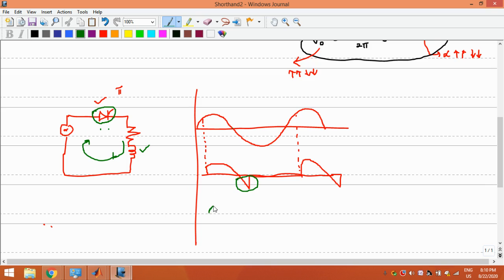So if you draw the current, I need to draw likewise. So this part is because of inductor, frankly saying. Again here no current, and then again this current will go like this. Fine. So this is what the current waveform is, in the case of an inductive load. So when inductance is there, definitely you will get a negative portion, right? Which is not recommended for good power quality or good power factor, because you have a negative part, current is in positive. So your net output power delivery will deteriorate, definitely, right?